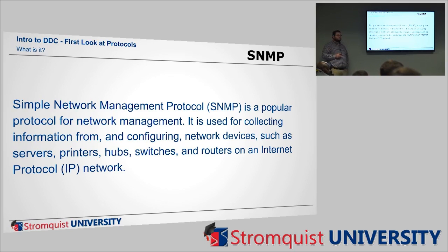You can't really tie Modbus to anything else, right? PLCs, they can communicate with each other on their system. If it's Modbus, you can get a Modbus driver for a Jace, and if it's talking Modbus, you can pull it in. It's still a standard protocol. So I can have one manufacturer's Modbus device talking to another manufacturer's Modbus device. But it can't talk to BACnet without some kind of gateway or a Jace or something like that. They can't be on the same bus.